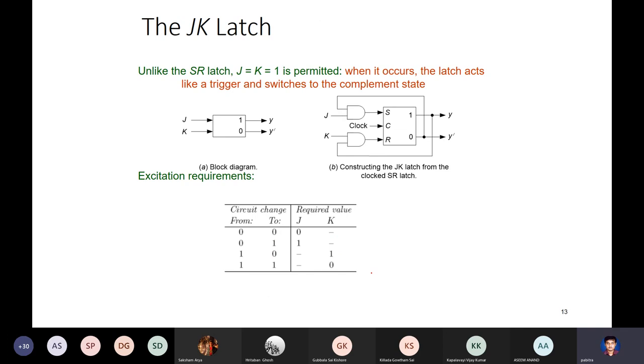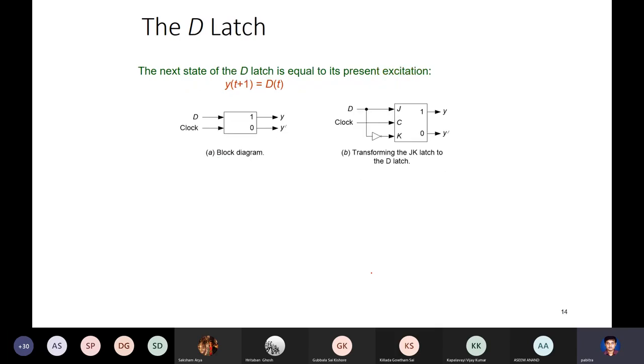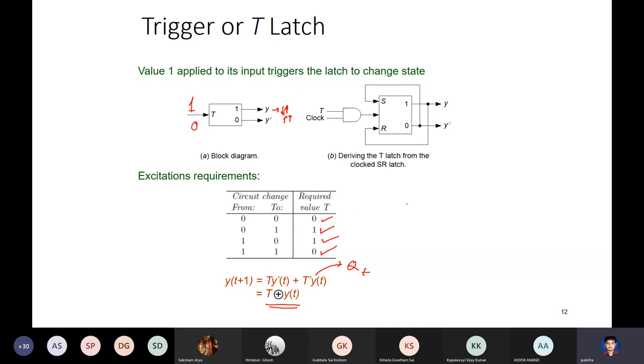Now let us look at another conversion of this basic latch. By the way, I'm using the basic SR latch with some additional circuit. Sometimes you can realize these transition excitation functions by a feedback circuit. That basic cross-coupling circuit has to be always there, but depending on what gate and what other circuit you choose, you may have a simpler realization than using an SR latch with this transition table. But okay, I'm explaining it using this.